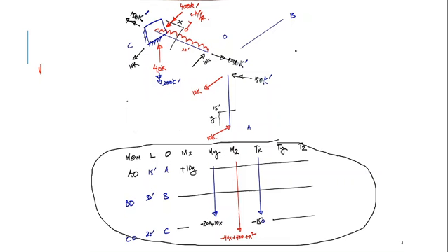Okay, before that I have to develop the free body diagrams. In this structure it's always a good option to start from a free end. So 10 kip is applied here, so I can apply a 10 kip that would be equal and opposite. It is in the Z direction, so it is also in the Z direction. Moving this 10 kip towards support O, joint O, will render a moment of 150 kip foot anti-clockwise. 10 into 15 gives us 150, and that would be anti-clockwise. So I have to apply a resistive moment, that is clockwise 150 kip foot.